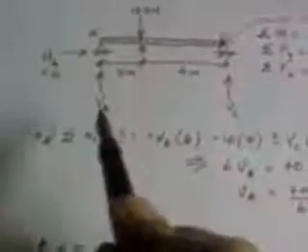So we put VC there. Now, for the sum of vertical forces, we don't need to multiply by distance, because it is not a moment force. It's just a force. If it's a moment force like this one, we have to multiply the force times the distance to the center of rotation. So in this case, we don't multiply by any distance.